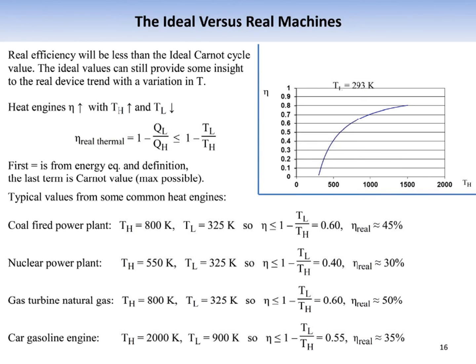So what we have is this formulation that Carnot efficiency is 1 minus TL over TS for an engine. So if we want to maximize it, we must reduce this term TL over TS to 0, and we will then be left with thermal efficiency of 1. For making this term 0, either we lower the TL to 0 Kelvin, or we maximize this TH.